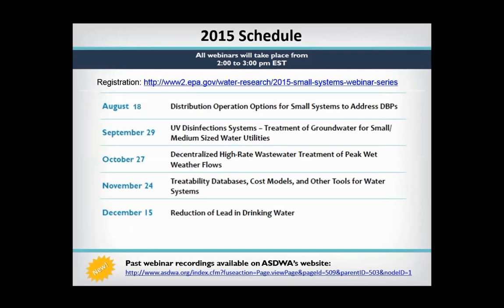Okay, here's one, Mike, that just came in. I have a very large municipal system with low copper levels, but also low dosage rates of orthophosphate and low levels in the distribution system. Should I be content with the low copper readings or be concerned with the orthophosphate readings? Well, I'm assuming from this question that it's not that the orthophosphate, well, I'm not sure why it's there, whether it's there for lead from brass and solder or whatever. I would guess that.